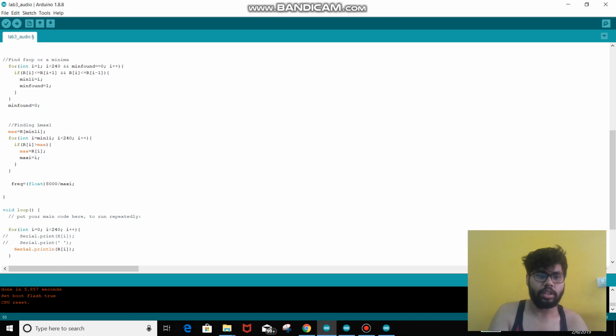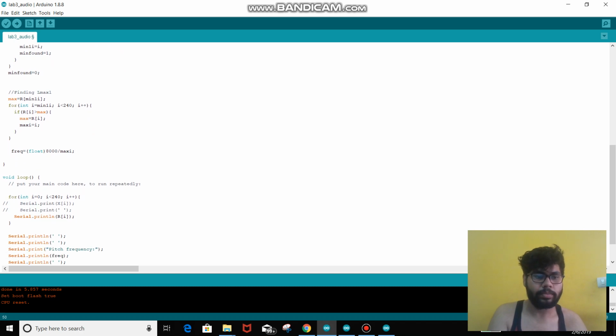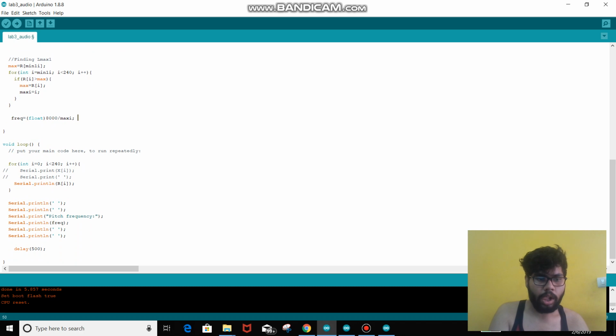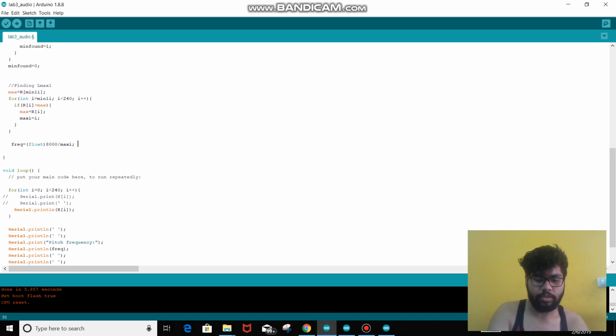So we substitute the 50 term by 8000 and the 60 term by 1. That is why we find the pitch frequency by doing sampling frequency 8000 divided by the index of the global maxima other than the origin data. So in this way we can also see the pitch frequency that we find here.